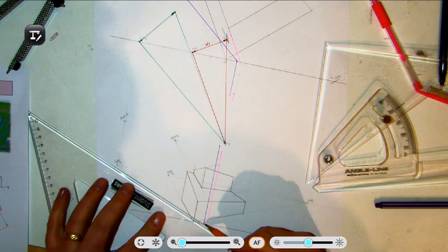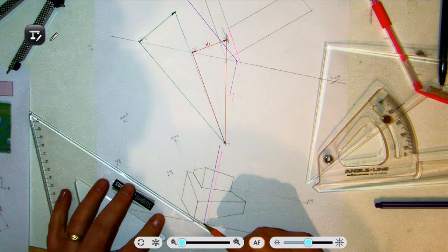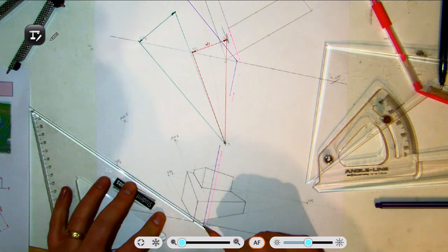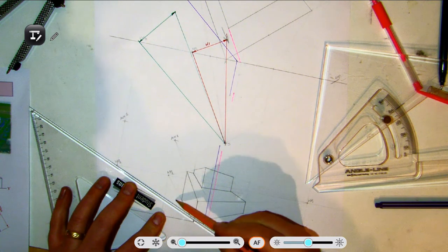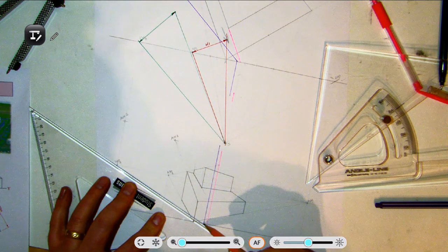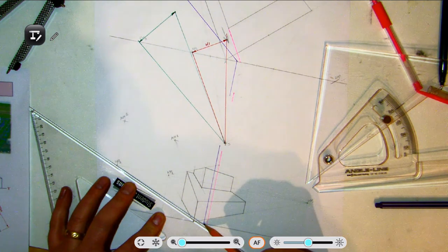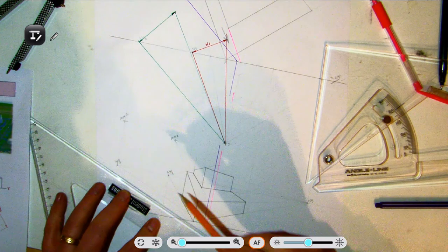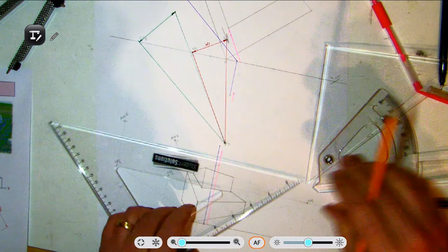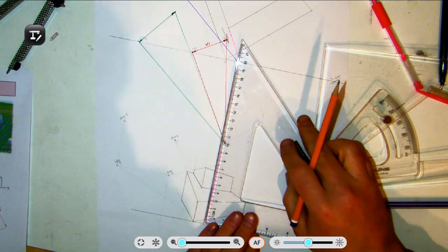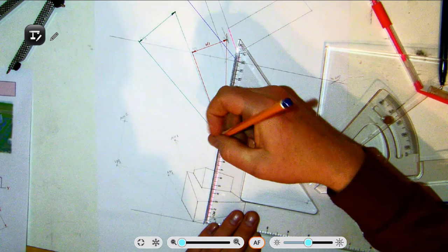And in this question here, what we're going to do is take this and join the base of the height line this time, because we don't have any base here, so we need to find the base of this tower as well. So we need to bring it back point 0 or height 0 back to VP3, and then we mark the height of the tower. So in this case here, the height of the tower is 100 mils.